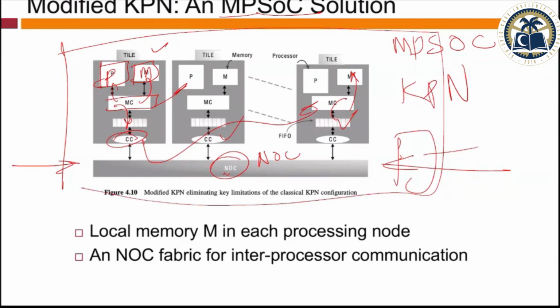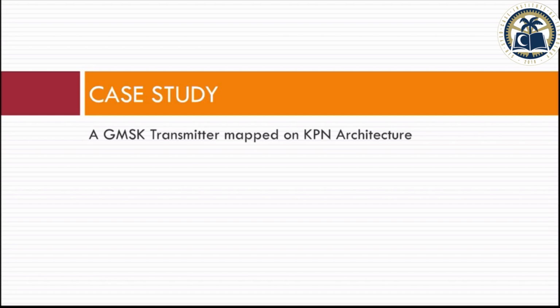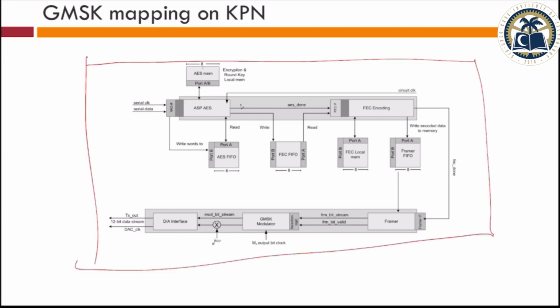And please remember that a mistake you make here will have very serious consequences, because you cannot go back and fix it, saying, no, I actually wanted to do KPN, Kahn Process Network. If you cannot handle this type of complexity, you are stuck, and if you then want to change your system level architecture, it becomes very difficult. So this has to be a very conscious design decision about how you are going to design your system.